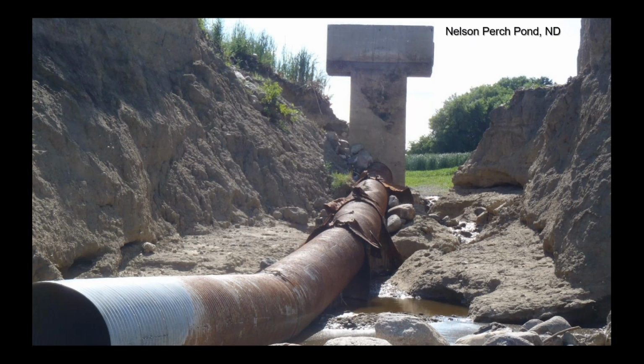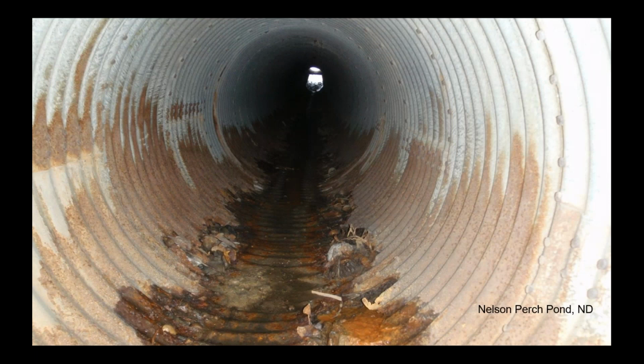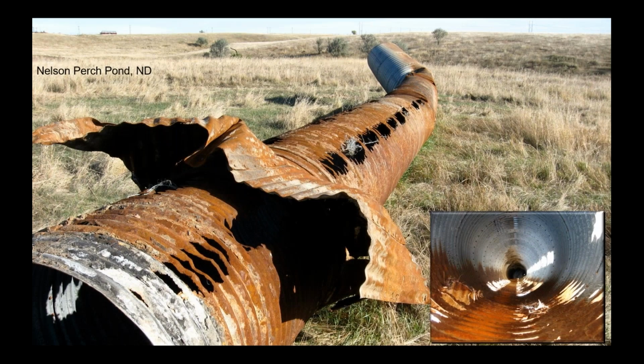And the root cause of this failure was the deteriorated conduit. Corrugated metal pipe has a service life of anywhere from about 7 years up to probably around 30 or 40, maybe a little longer in some conditions. But of all the pipes, a corrugated metal pipe has the lowest service life. And in this case, when they pulled out the pipe, you could see the whole bottom was rusted through.